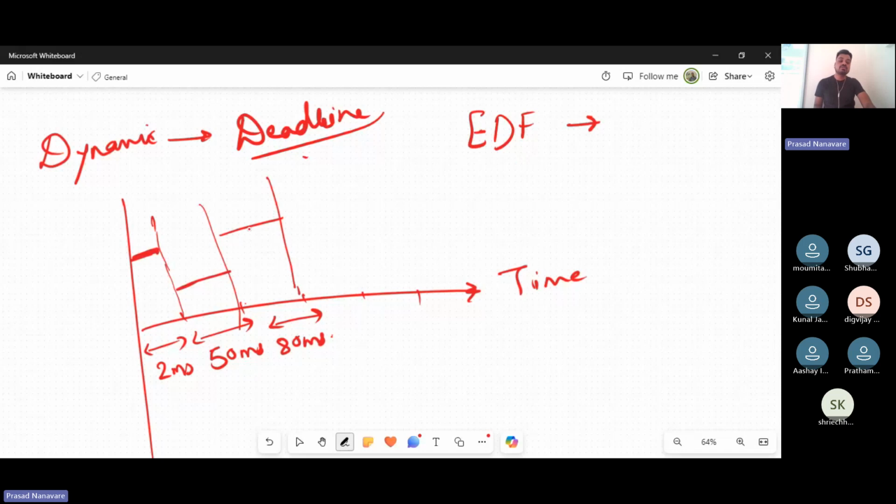And if we are talking about rate monotonic scheduling, how it works is that the lowest period task will run first no matter what. Okay, the lowest period task runs first. It could have the low priority, but if we are saying my application, my feature, my code should run on RMS, rate monotonic scheduling, then the lowest period task gets the priority and runs.